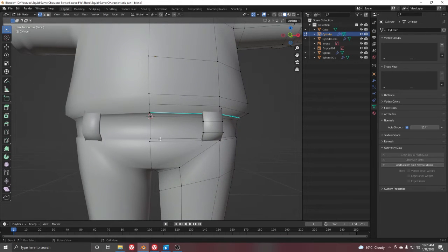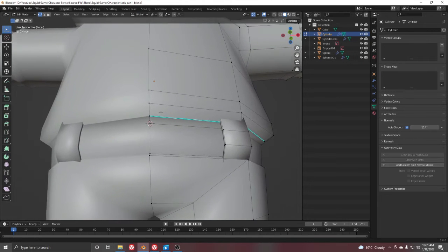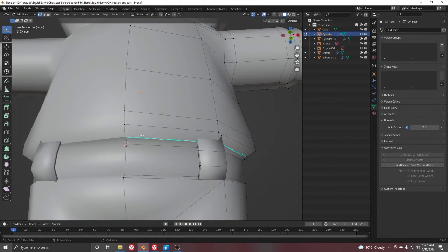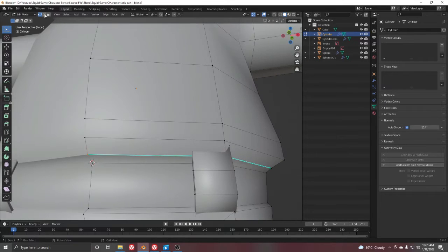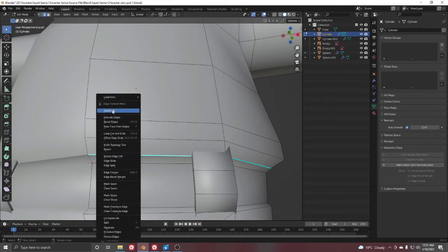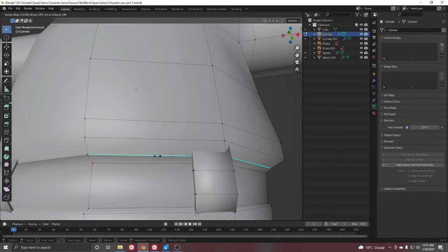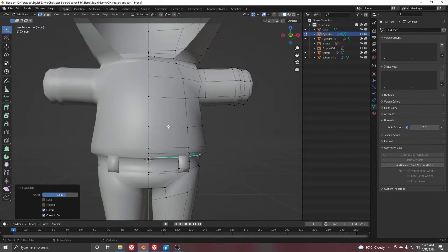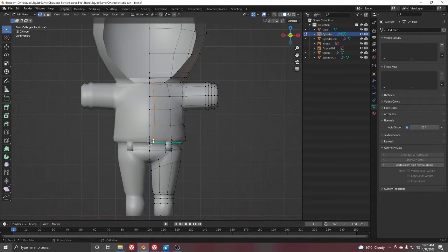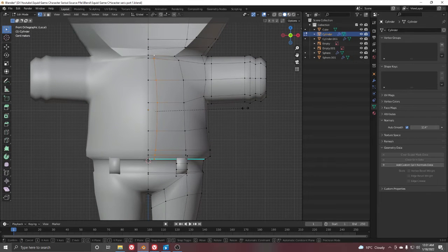Okay, so I want to end up my zip here, so I will just select these two vertices, or you can easily select this edge, right click, make it subdivide, go to vertex and just move this one vertex around here with double G. And now if I just select these two vertices and press J, I can join it like this. We can also make this line straight, so for that S, X and 0 to make it straight like this.